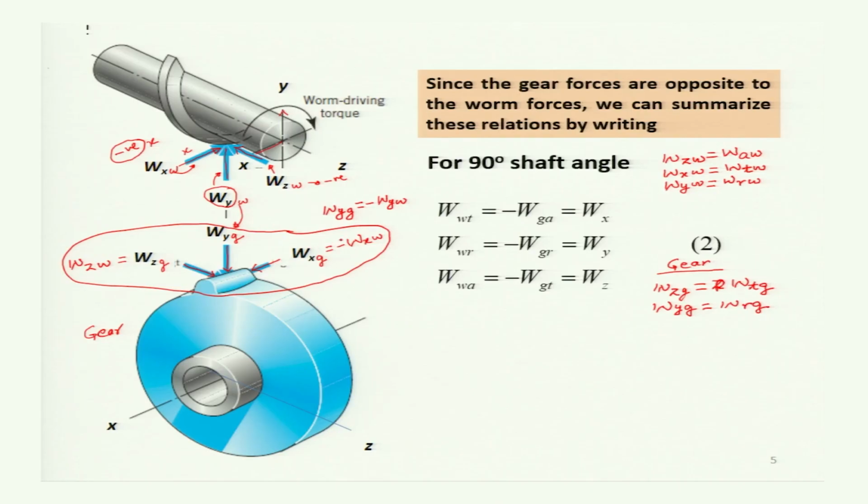And for the force acting in the direction of x, for the case of the gear, x is the axial direction, and so whatever force is acting in the x direction will be the axial force. So Wx gear will be W axial gear.